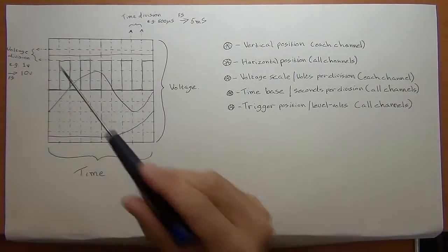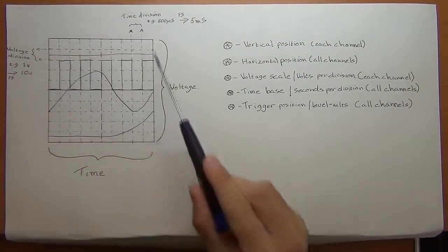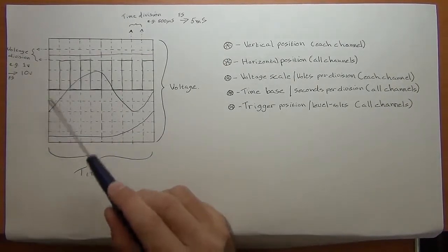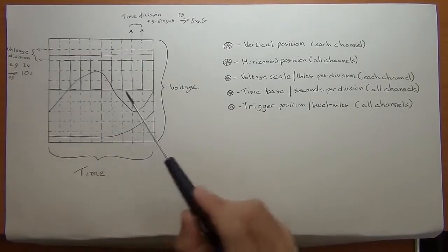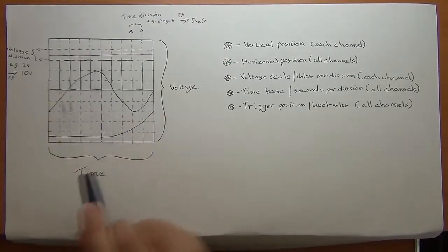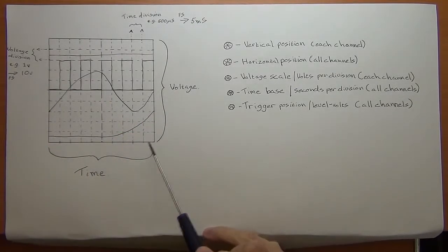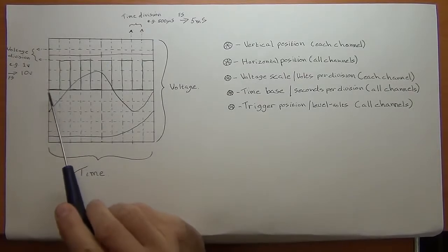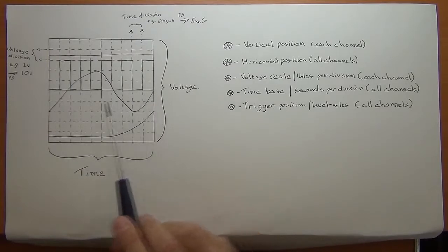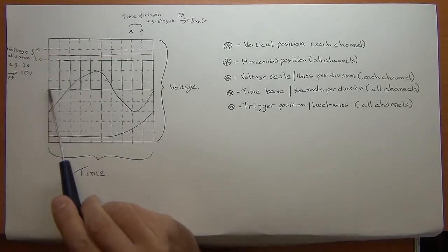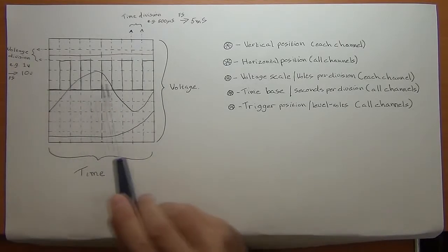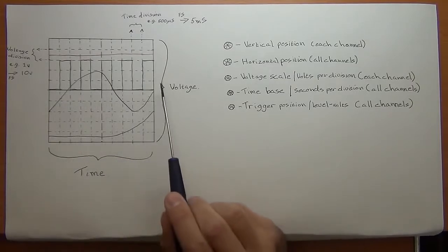Right, so let's just cover off what on earth we see on the display and how that actual display works for us. Now don't be too worried about the images and what I've got on this display. We'll cover that in a moment, but let's first of all look at the matrix of lines on the oscilloscope display. Now probably the first important thing, as I mentioned with this little time machine, is the fact that you can represent time by the horizontal line, or the x-axis, going along here.